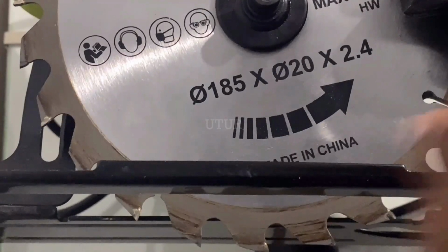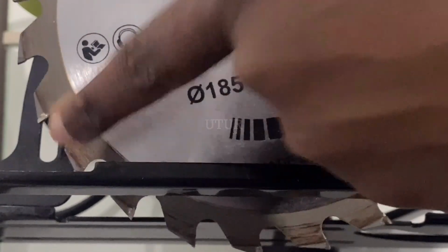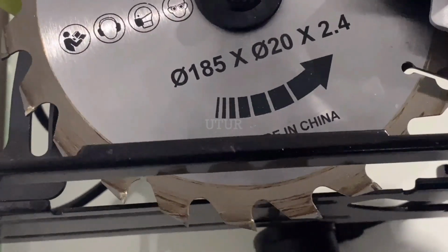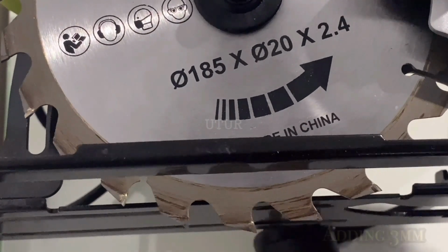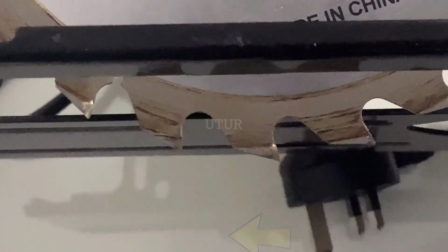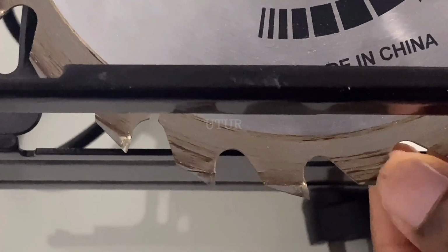So I would be using it to get the job done, but not overly extensively, as I do not want to compromise on the integrity of the blade. I would try as much as possible to keep my hands steady whilst cutting strips off of the hard plywood. And I will also be adding 3mm to the depth of my cut so that the blade can cut through the hardwood plywood material at the base here.